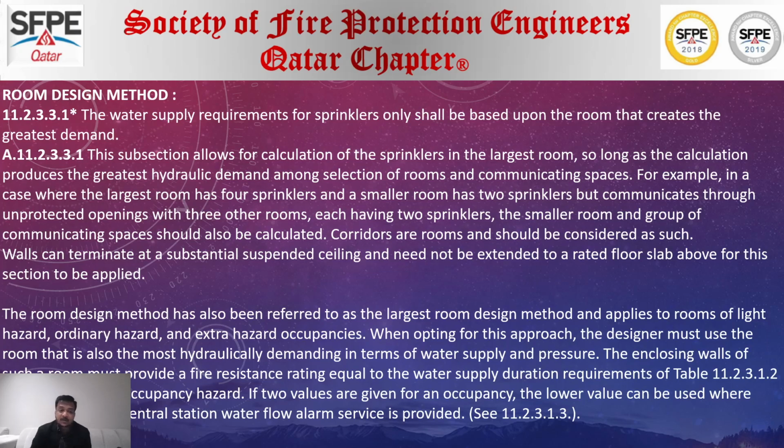There is another methodology called the room design method. The room design method is used when you have a series of rooms in a floor of a building, and these rooms are fire rated for 2 hours. Then the water demand will be chosen based on the most remote and most demanding room in the particular floor.